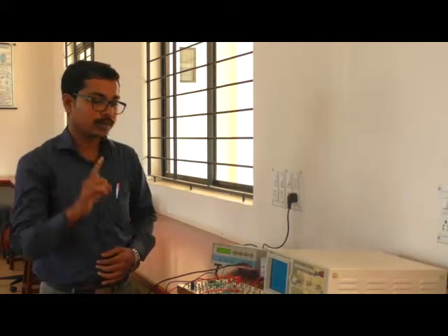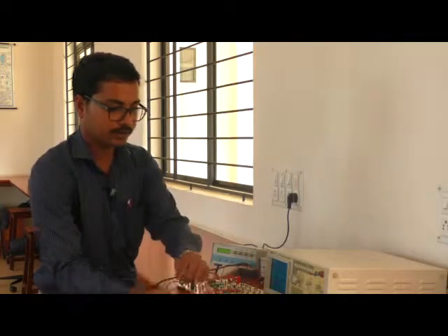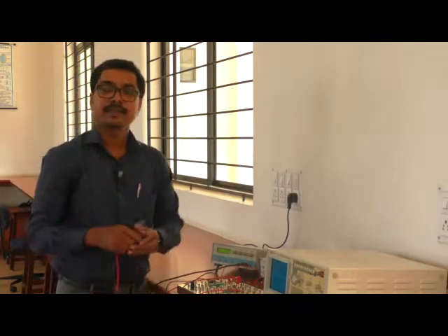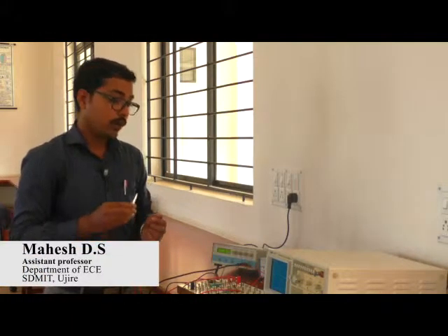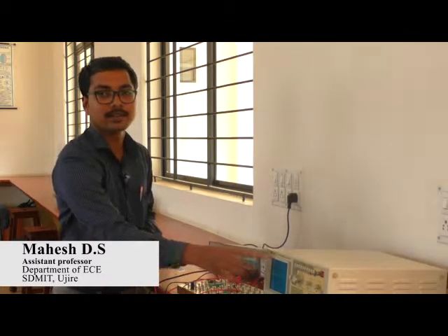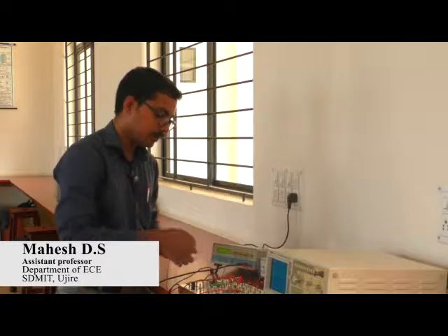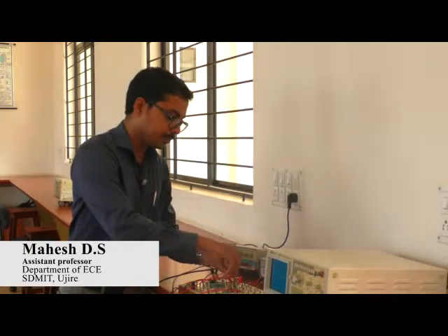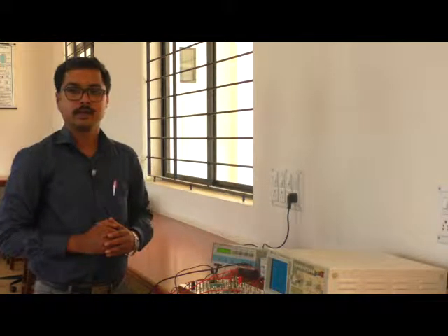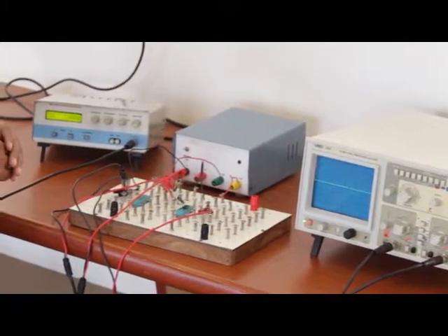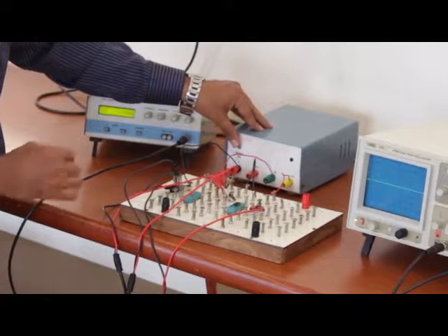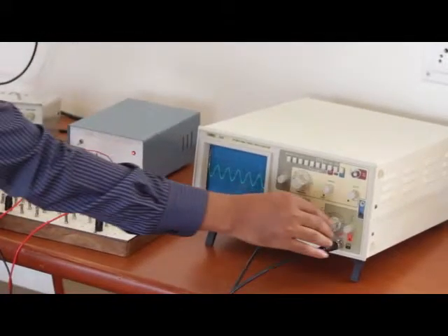I have to take one reference, called the comparison voltage. What output I am getting with respect to what has to be shown on the screen. Whenever you are comparing any signals, there should be a reference input. So I am taking that reference input from pin number 3 itself, that is the input. This is how the circuit is done. Now we will turn on the supply, that is the biasing voltage, and bring the output.